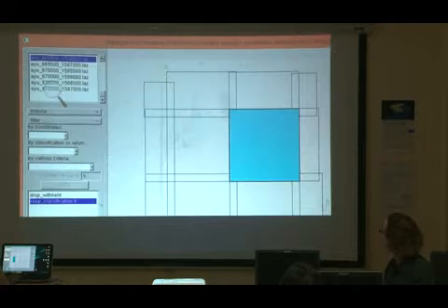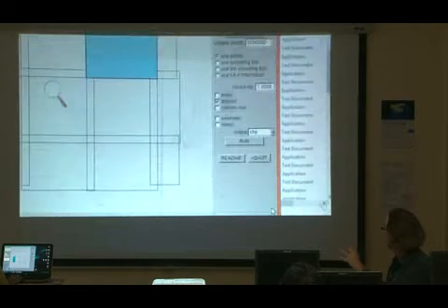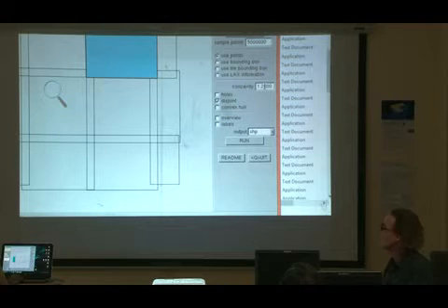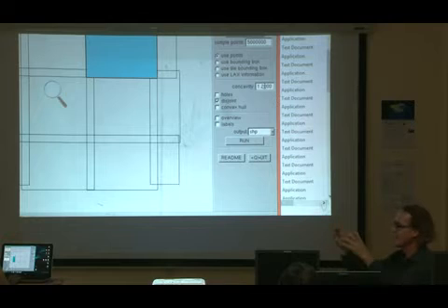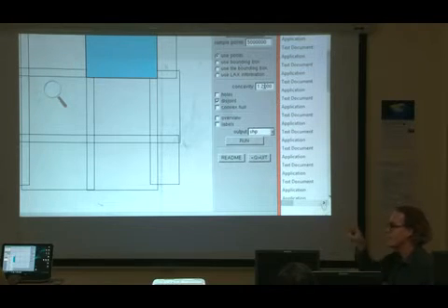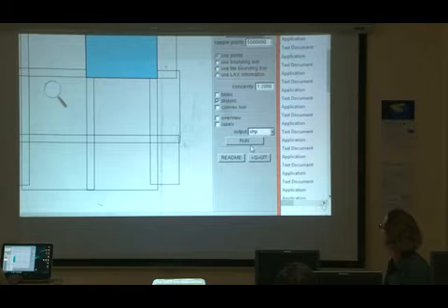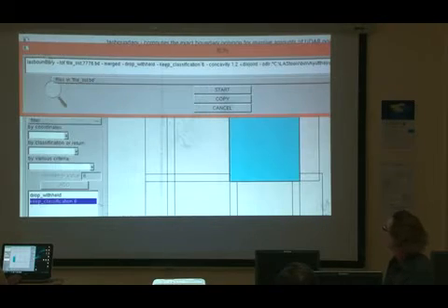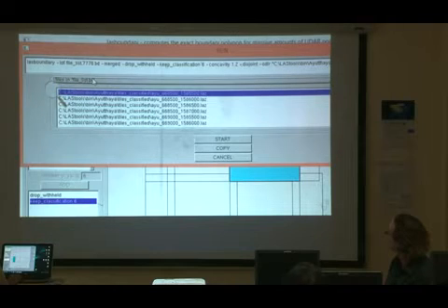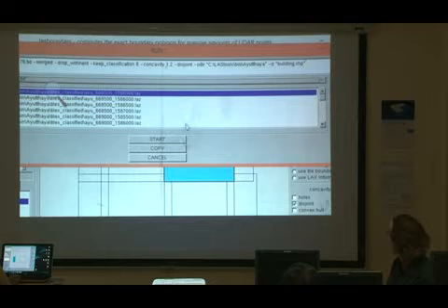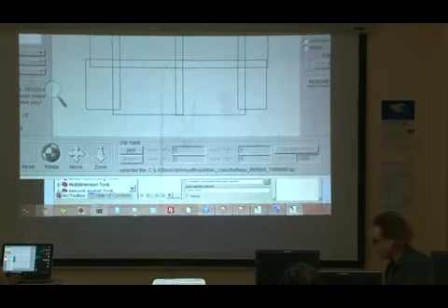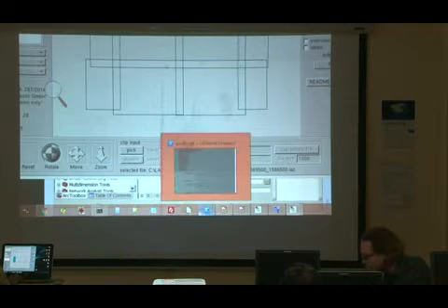Then it will compute a triangulation from all those points. And then delete all triangles which have edge lengths 1 meter 20 or bigger. And all the remaining triangles are like islands around buildings, and it will make polygons around. So this will be our first LiDAR derivative. Start. And I'm already now starting QGIS.